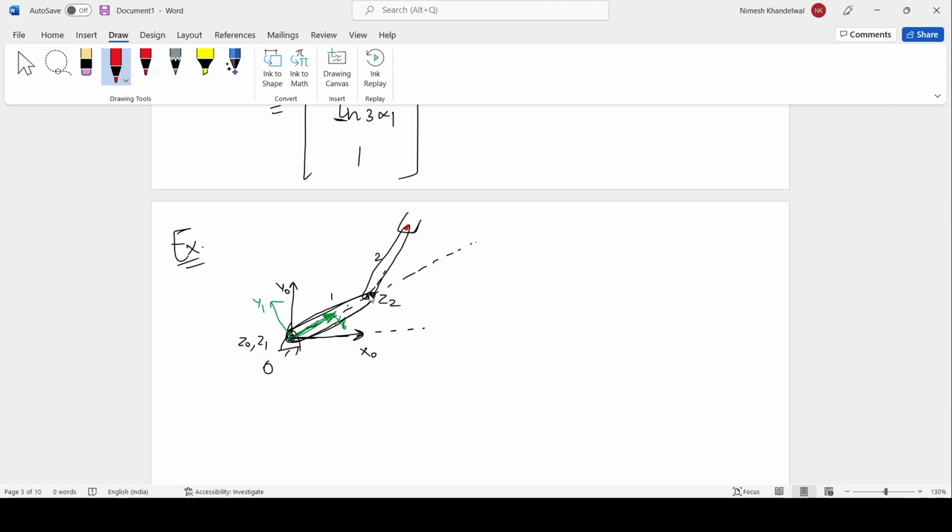We only know about the z-axis, so we say there is a z3 axis on the end effector. So x2 will be along the second link, connecting z2 and z3, and then we can know y2. Since frame 2 and frame 3 are parallel, we get x3 and y3.